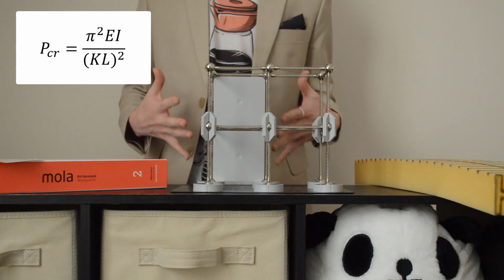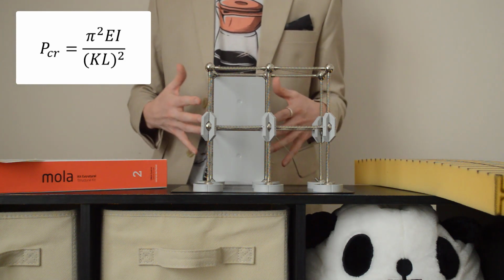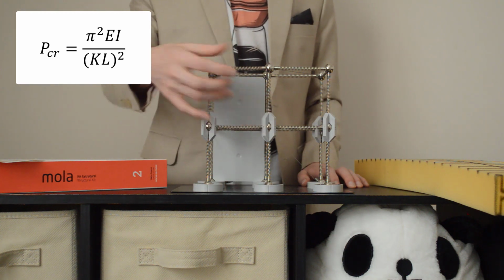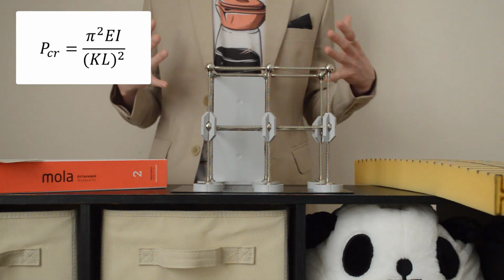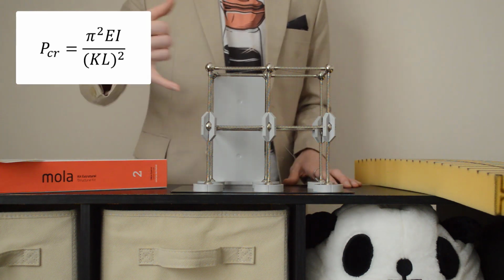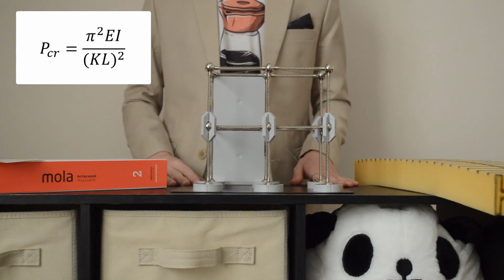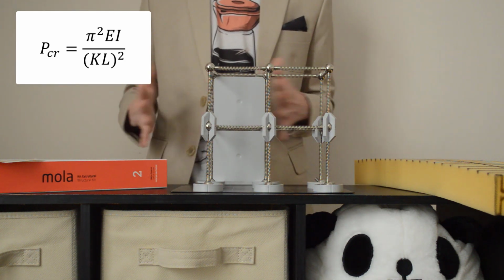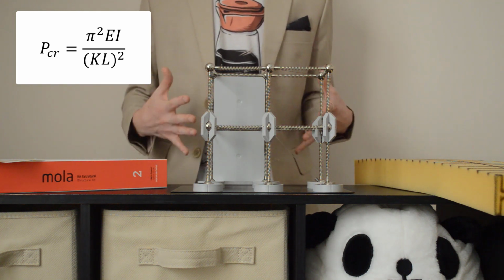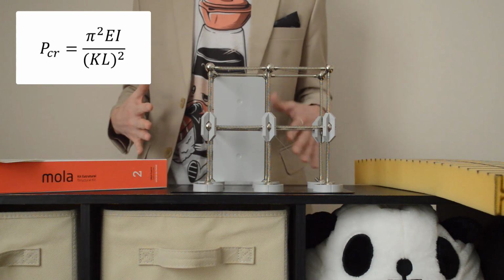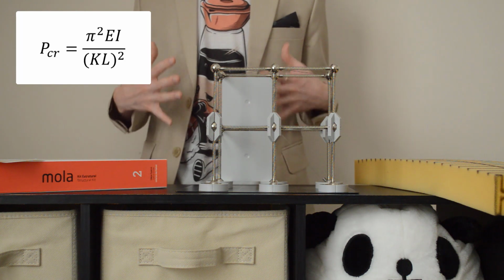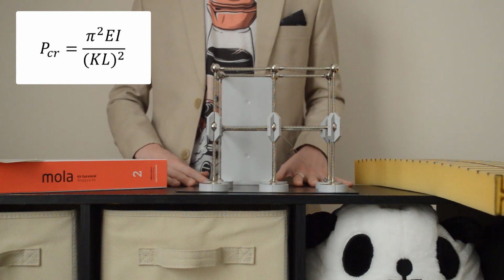Well, now we have created a scenario where we have a weak axis with a small moment of inertia, but a shorter unsupported length, and we have a strong axis with a large moment of inertia, but also a larger unsupported length. So which way would that column buckle? Well, in that scenario, we would need to run the numbers about both axes. The small number, of course, would be the controlling value that determines the overall strength of the column.